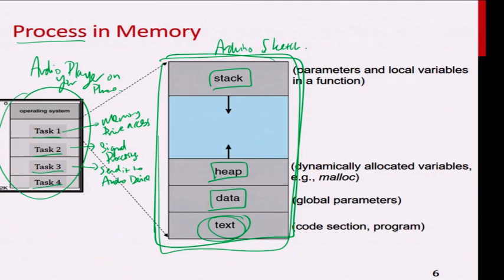Again, don't think of this as sequential. It's not sequential. Everything is running in parallel. Once I read from the memory, I do not need to process the whole thing at the same time. I can process 5 seconds at a time and make sure that within the next 5 seconds, this data goes out. That's how you see buffering on your media player. I do not necessarily have to do one task, then the next task. I can do it all in parallel, as long as the end user, the person hearing the music, does not hear any interruption or break. Then I fulfill my real-time objective.